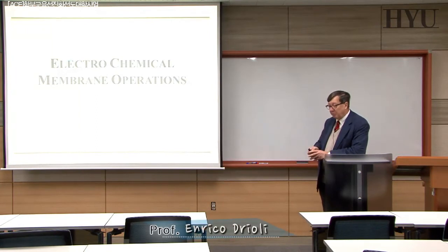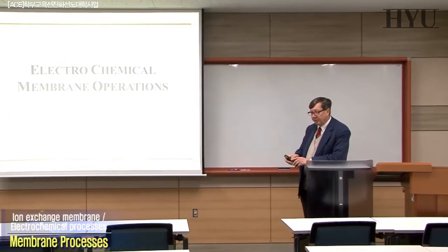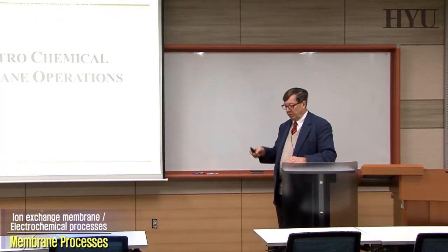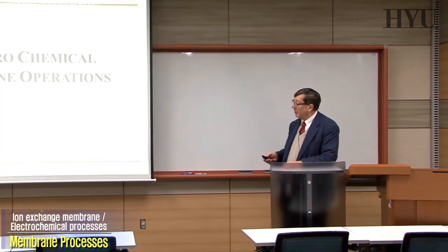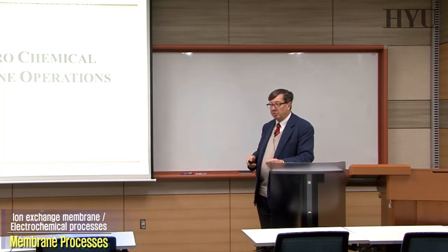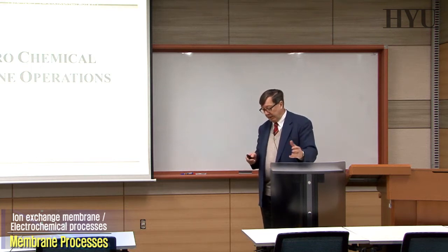In this area, we are using membranes which are totally different from the ones that we have been discussing until now. And you will learn also how to prepare this kind of membranes. These are charged membranes, in which the selectivity is not related just to solvents or to molecules like sodium chloride or potassium chloride, but to the transport of ions, NH4 plus or potassium ions or hydrogen ions, etc. Not just molecules, but single ions.